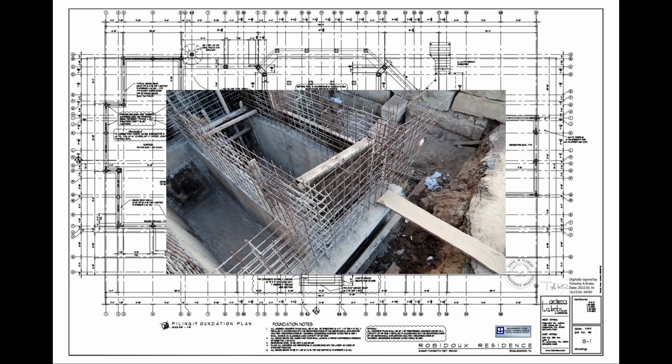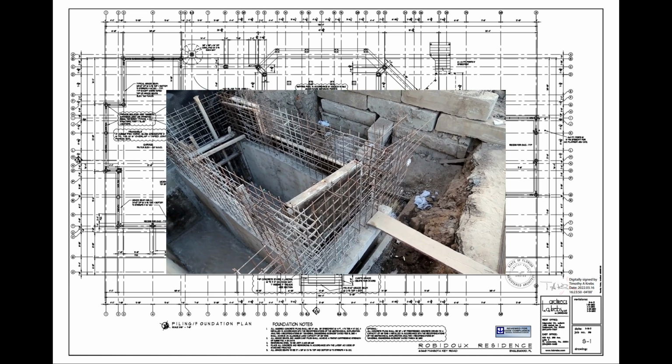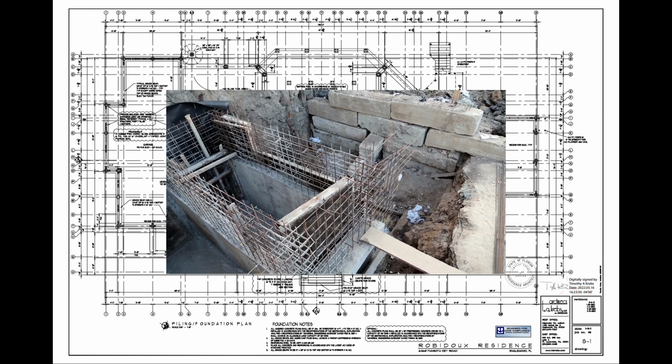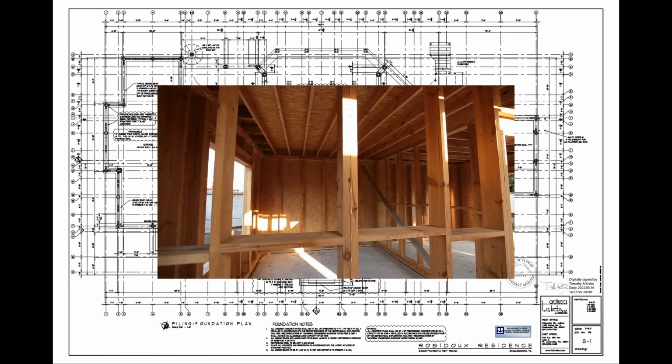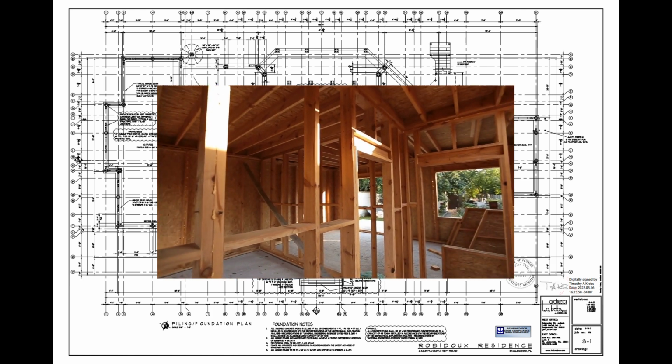Structural sheets are very similar to architectural sheets. They may show floor plans, elevations, and section details. In addition to these, there may be foundation plans as well. Foundations are the part of the building that holds up the rest of the structure above. The difference between architectural and structural pages is that architectural sheets show more of the design elements and structural sheets show the structural details such as concrete, framing, steel, and other structural elements. S sheets can also have schedules, although they are more likely to be foundation schedules, wall type schedules, beam schedules, etc.